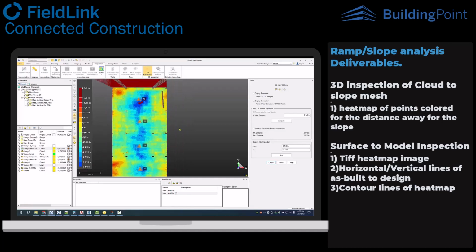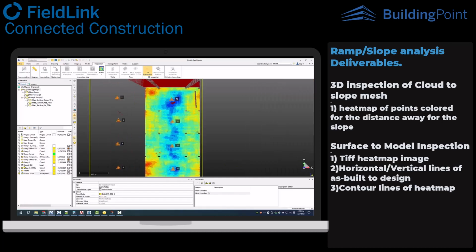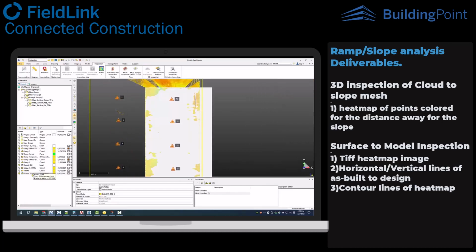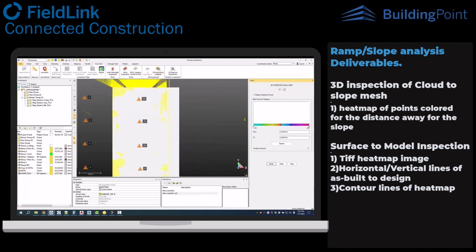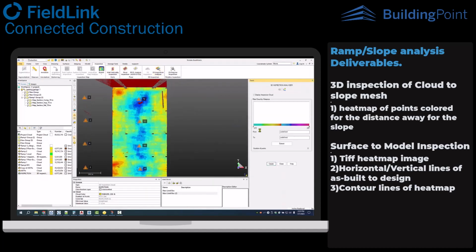This is going to show you the entire floor though, which if I'm the concrete guy, or sometimes even the GC, is not always necessary or what needs to be done to make spec. I am going to create this as an inspection cloud, so I can export that out with those same colors as an IFC. That's our first deliverable, or I can come back here and simply take images with that scale bar, which I also like to do. So that's your first step.